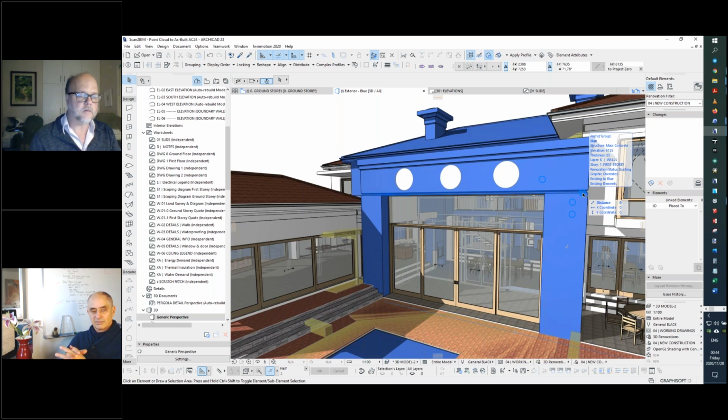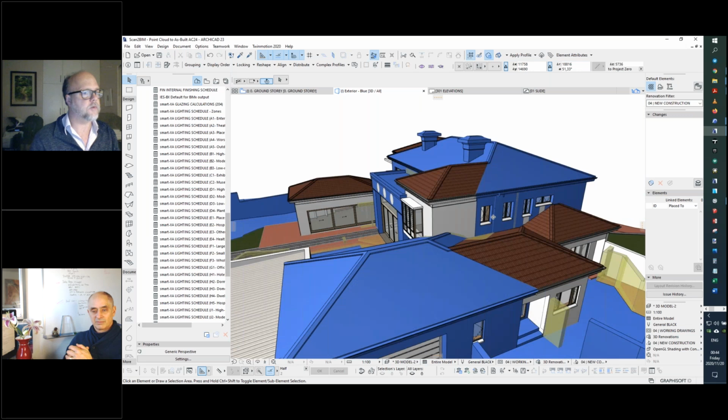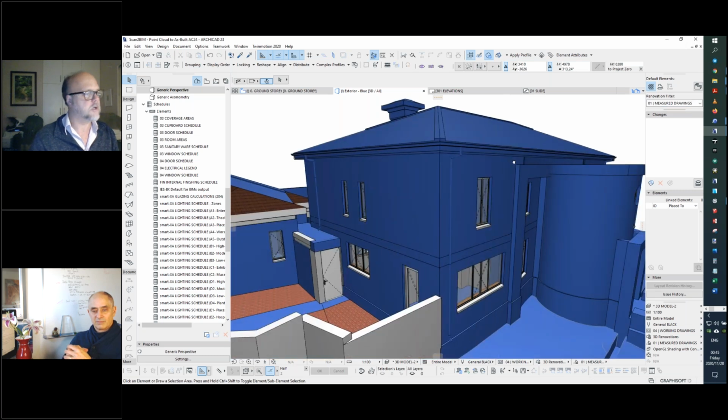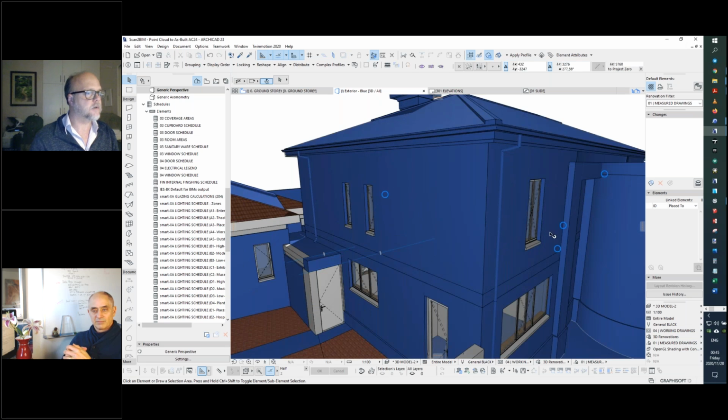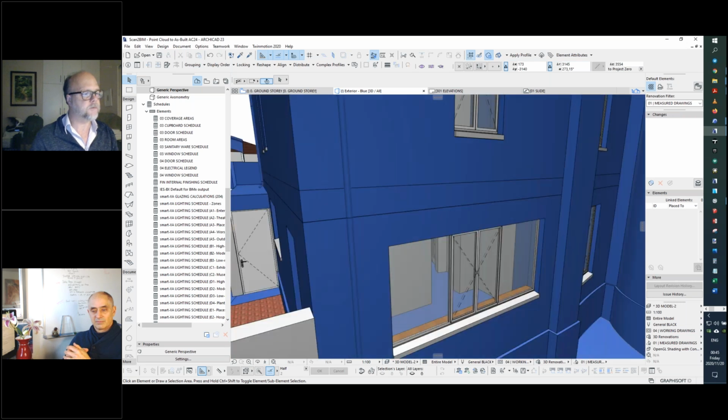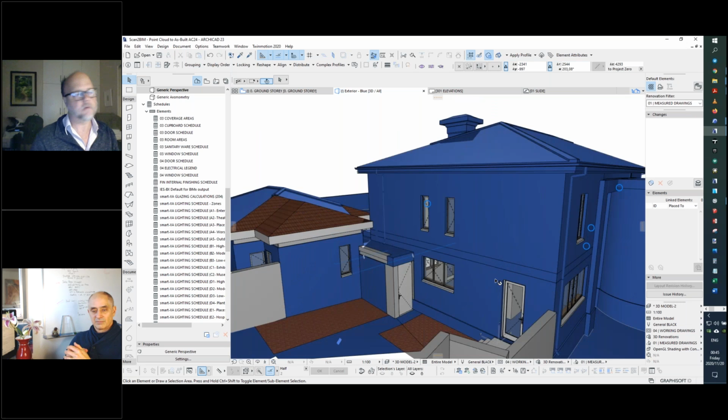With a point cloud and virtual tour combination scan, you don't need to go back to site. I did this without being there. The model from the point cloud with this low level of detail took me 2.5 days to model for as-built. And the model that I delivered was an LOD 300 detail level model. That means the gutters, the downpipes, the windows are modeled according to the actual windows. It's not just a single hole in the wall. The built-in furniture, sanitary ware, everything is built into the model as per the existing conditions on site, LOD 300.